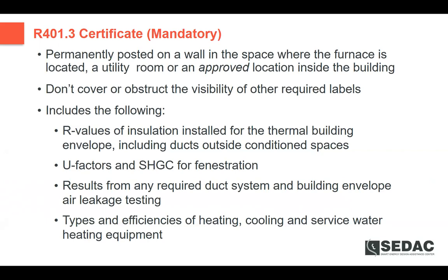Particularly as we get later on to equipment sizing. If you end up putting in windows that are worse than the original construction, you could end up with a deficiency and a comfort problem, not only from the lack of insulation in the window, but your heating and air conditioning system may not be able to keep up either.